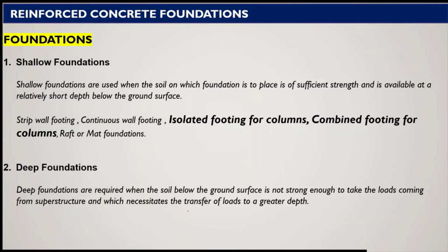So that means if the soil beneath the wall or column, whatever be the mechanism to transfer the load, is not strong, not having sufficient bearing capacity which can take care of all the loads coming from the superstructure, then we have to go deeper into the soil so that we can come across a soil having suitable bearing capacity, or some solid type of rocky material is available where we can transfer the load.